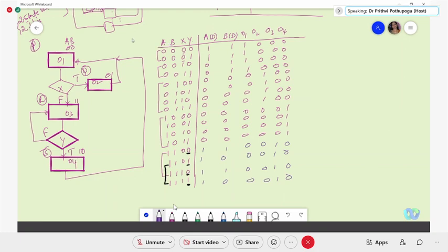Up to the size of 2 power 5, defining the table will be simple and easy. If more states or more test variables are there, maybe we go for the choice of either mux or one hot. If there are more states, maybe mux can be the most suitable approach. So it is left to the choice of the designer.